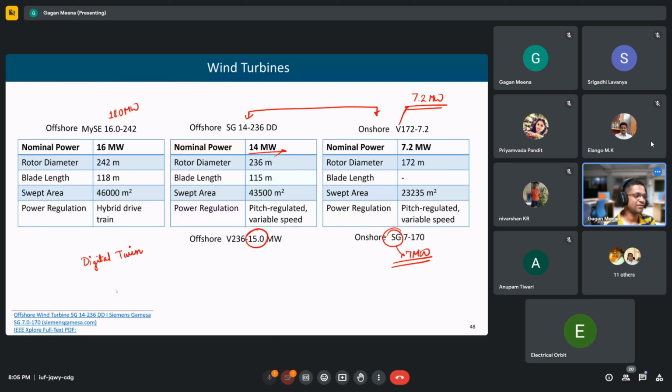Generally, if there is overproduction from solar or wind, then they simply have to curtail. That is why they are planning to put in storage. When there is overproduction, they can store the power in a battery and then provide what they call RTC, round the clock generation. They can provide that RTC even when solar irradiance is low.